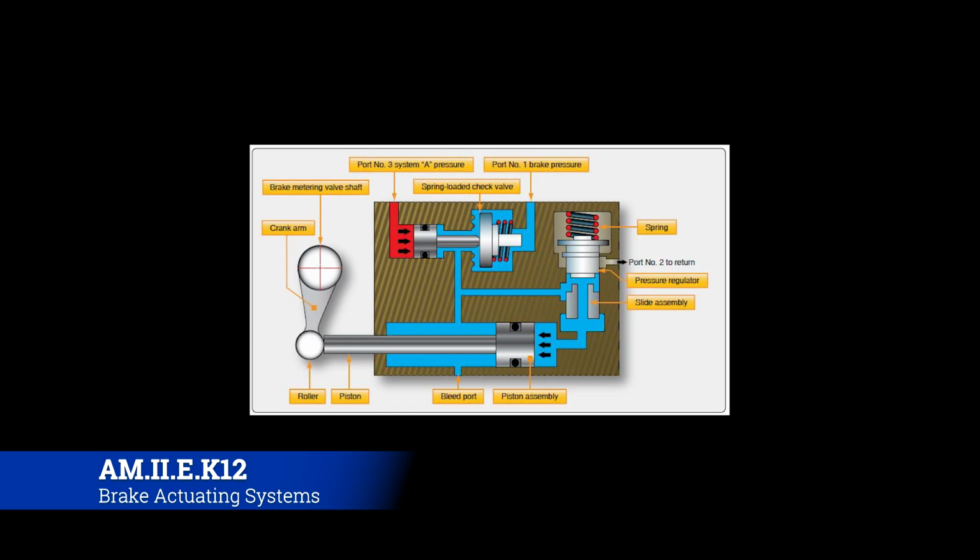So let's say you have brakes being applied in the cockpit at 100%, we want to stop, but there's a disproportion, or there's 50 psi on one side and 100 psi on the other side, then that plane's going to want to make a hard left-hand turn, because one side is going way faster than the other side at that point. And so those types of systems are there to make sure that doesn't happen. But that's a real high-level overview of a power brake system.